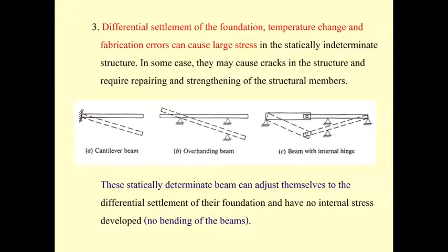The differential settlement of the foundation: if you have the beam with the fixed support as before, you may demonstrate this easily by holding your ruler very stiffly, and then you move one of your hands downward, and what you see is the beam is going to change its shape to something like this.